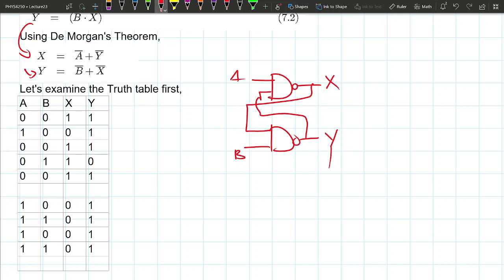So what I'm going to do is I'm going to change the A input from 0 to 1 and see what happens, okay? If I did that, right, so this is 1, B is still 0, okay? So Y, right, since Y is 0, since the previous state is Y, we know that this is going to be 1, this is going to be 1, right, because this is directly connected, right?